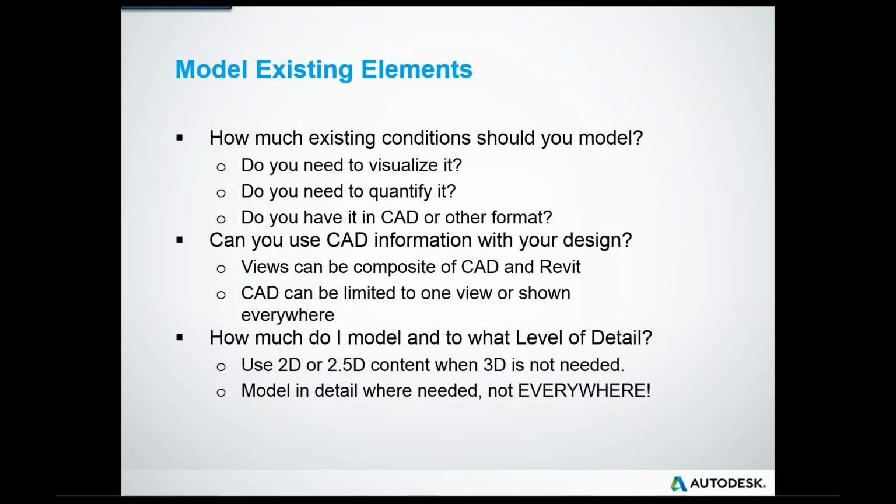And one of the things I believe in, again, is reusing your CAD drawings in an environment where I have considered a hybrid approach, where I bring CAD and Revit into a project. CAD can be limited to one view or be shown everywhere. And basically, the question I always get asked is, how much do I model and to what level of detail? I personally use 2D and 2.5D content when 3D is not needed everywhere. And I model the detail information where needed, not everywhere.